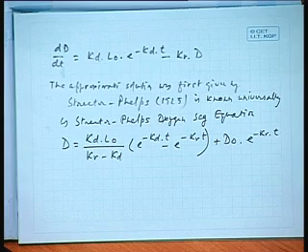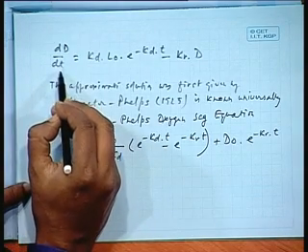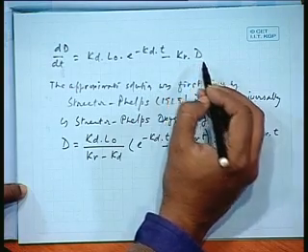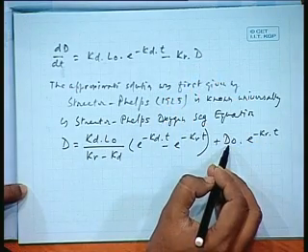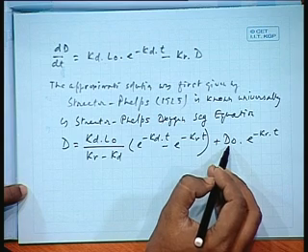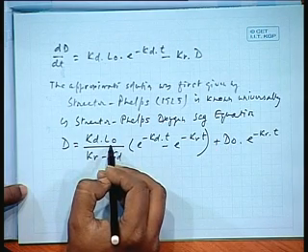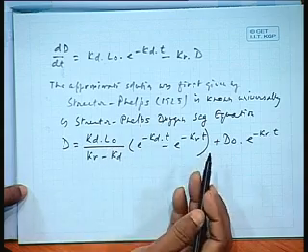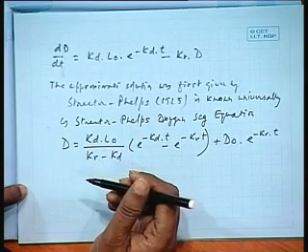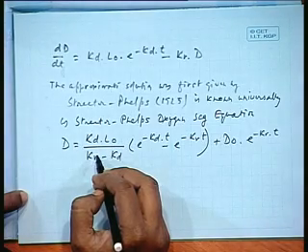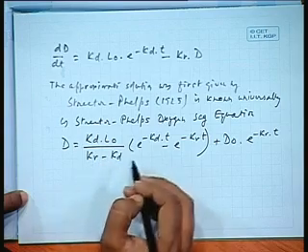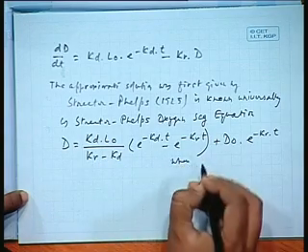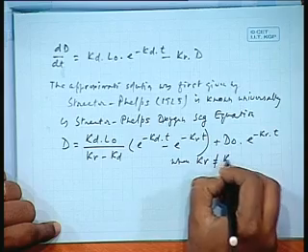Remember this: it is the typical approximate solution of this differential equation, considering that D is a function of D0, the initial deficit, and of L0 and kr. This is the solution we get when kr is not equal to kd.